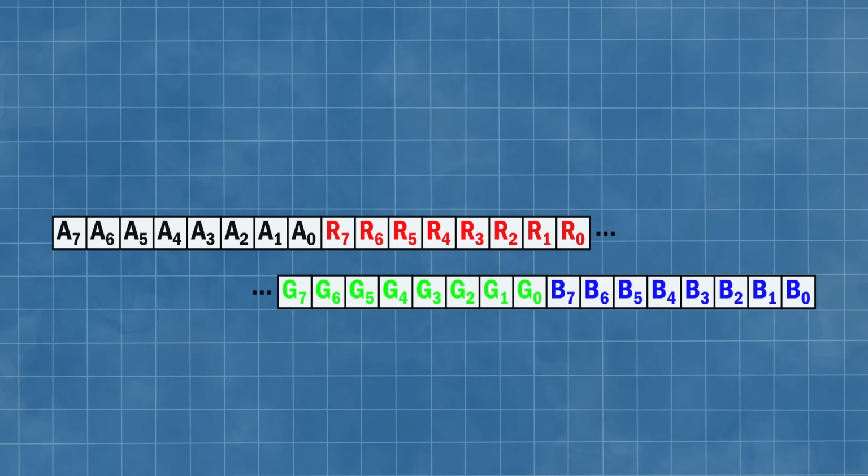Another common option is to use an alpha channel to describe the opacity of the color. The color format used for this is ARGB8888, with 8 bits each for alpha, red, green, and blue channels. To determine pixel color, you mix the object's ARGB value with the existing value. Displays can't show alpha, so before setting the pixel data, you need to do some math to convert to the appropriate RGB format. Now this can get quite complicated, so I'll leave you to research it if you're interested. Let's talk about drawing primitive shapes.